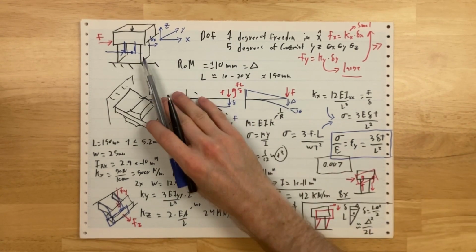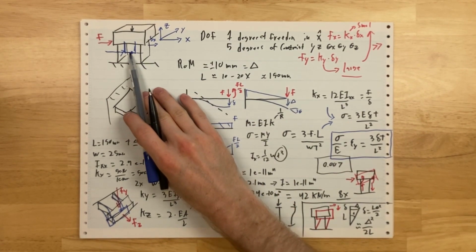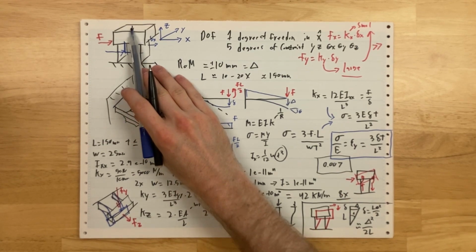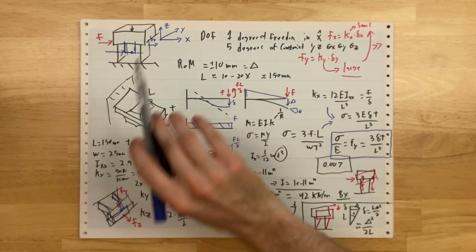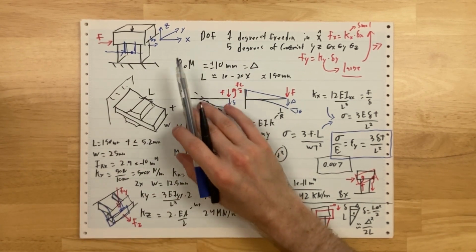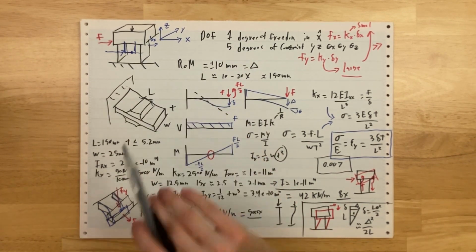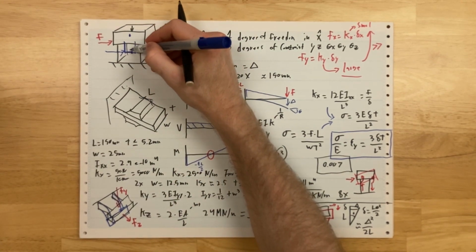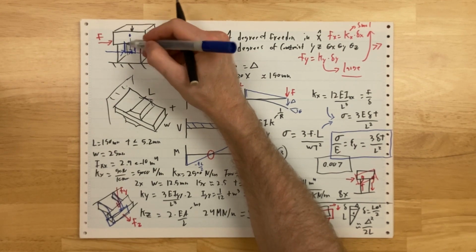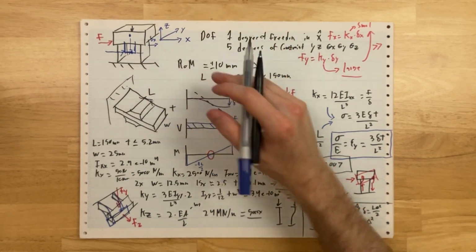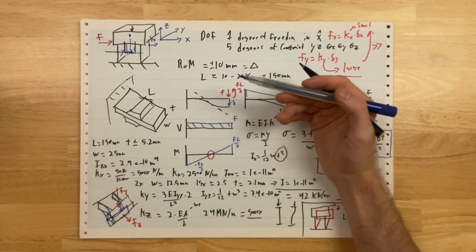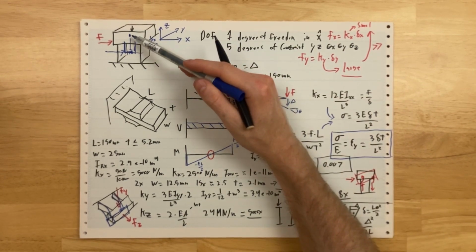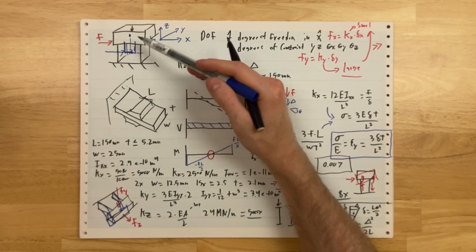The problem is this only works statically. So the center of stiffness is right here. That's where you should be pressing. But the center of mass of the system might be much higher. So if you're pressing at really high frequency, let's say you have a voice coil driving it, you're no longer putting those forces into the center of mass, which means at high frequency, you're basically creating these high frequency torques around that lever arm that will cause the whole system to rotate. The only way to make this work well at high frequency and at kind of low frequency static is to make the center of mass at the center of the stiffness and drive there.